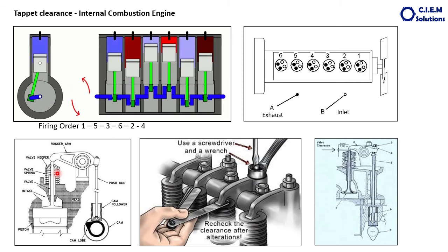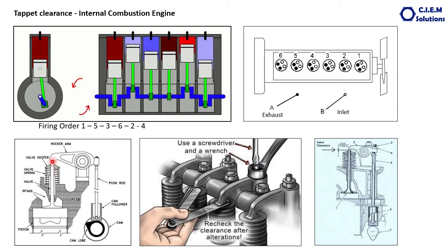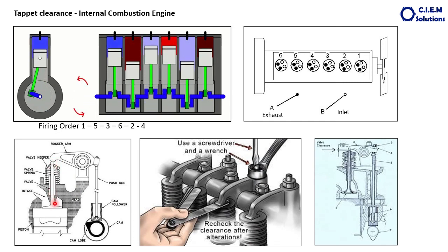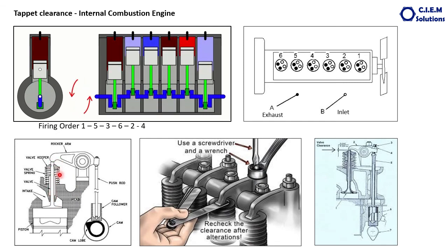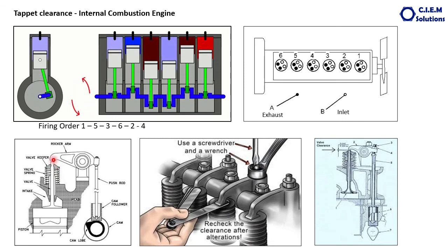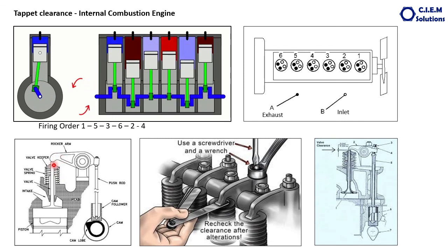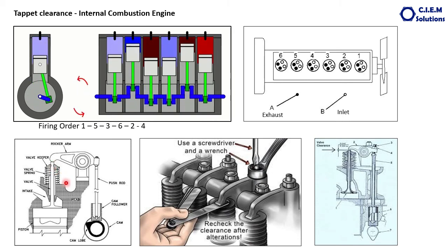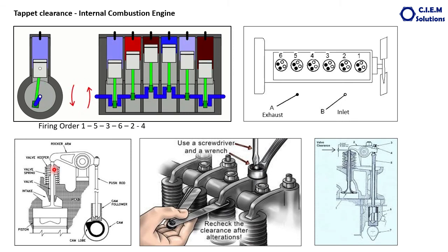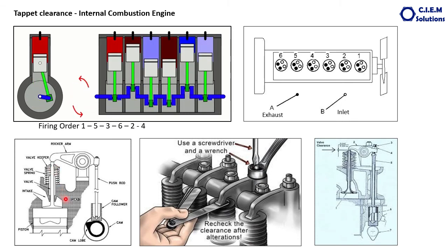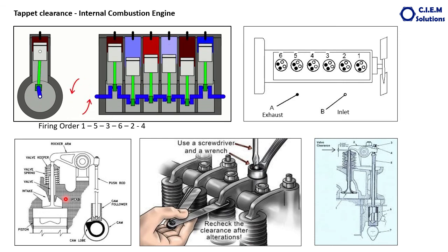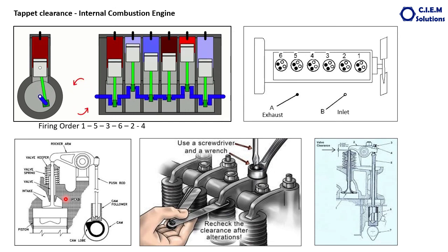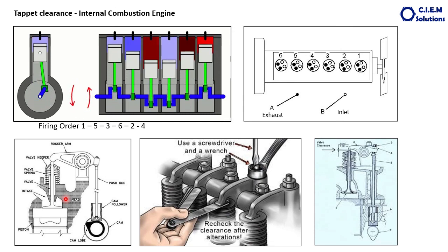What happens if the gap is more than the recommended? There is a delay in opening of the valve, which is another issue. And there is noise: when the gap is more, there will be huge noise. When the noise is more, friction will be more, then wear and tear will be fast, then again the gap will increase further, with some other consequential damages in the engine. So a specified gap has to be maintained, and the tappet setting has to be performed at recommended intervals